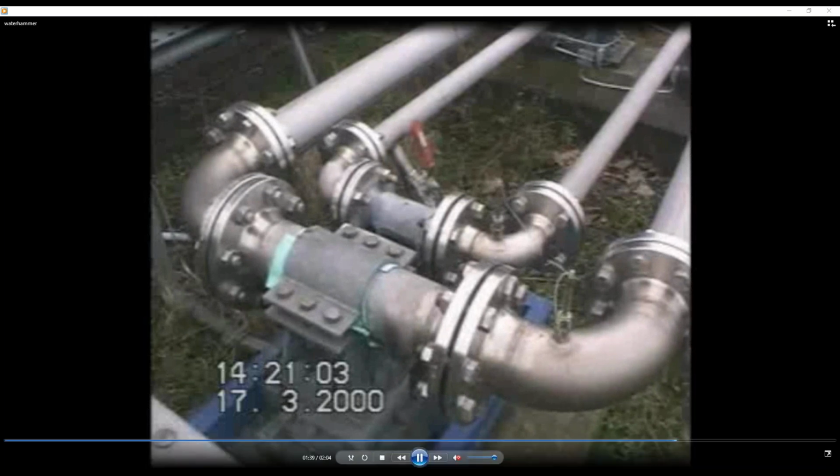Okay. So what we're talking about is, in a situation like what we're looking at right now, what is that transient wave doing between these two elbows? What force is it exerting on the piping, and what strength of support is needed to keep the piping from moving or just having to react to handle that? So you don't have damage to the supports or to these, like for example, there's flanges in here as well.